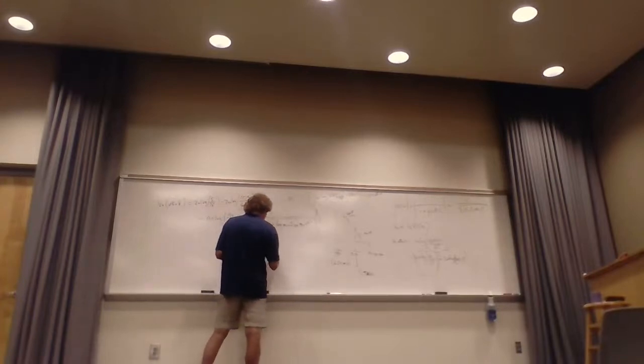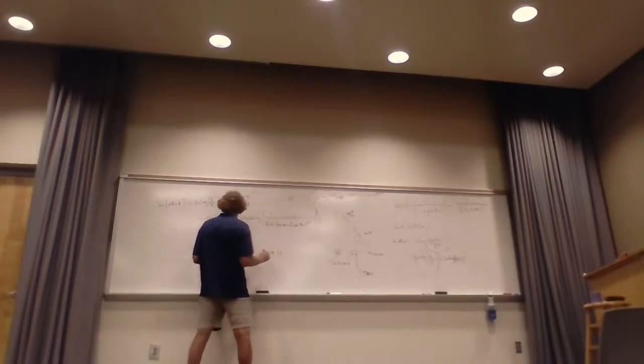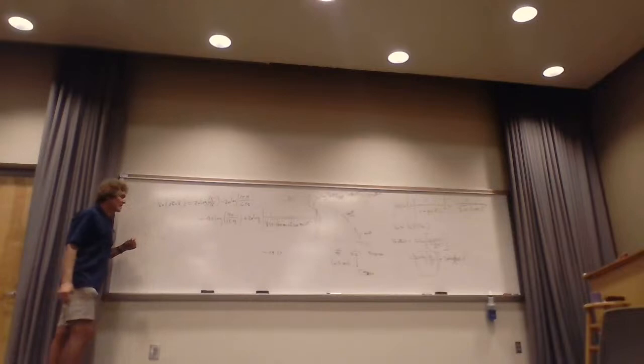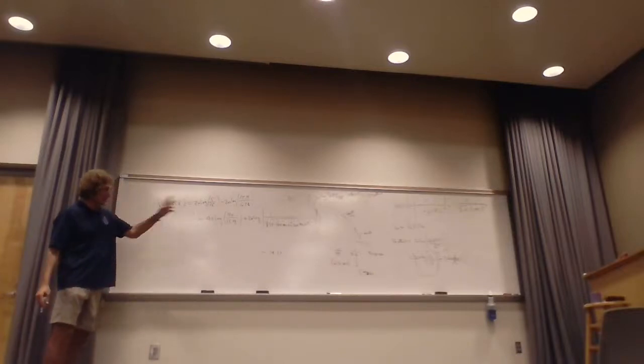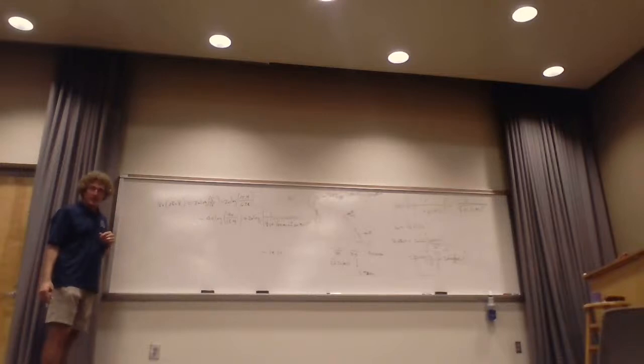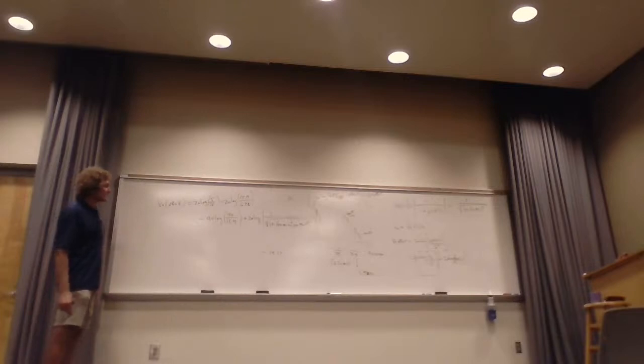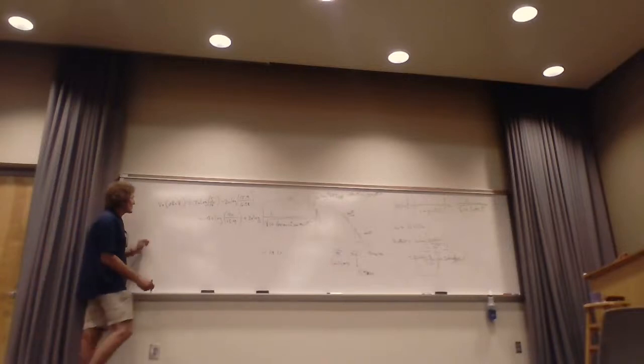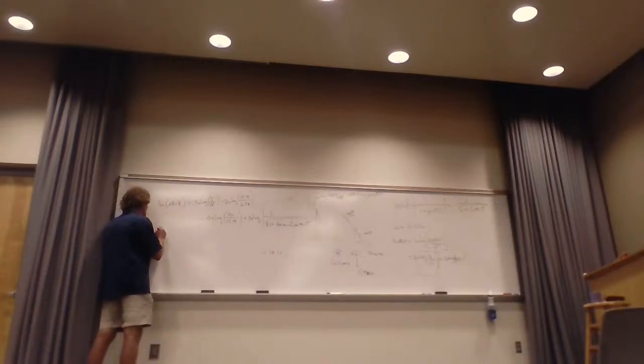This is about minus 19.18. And the rest of it, I forgot what it is, but I wanted to make sure you understand. That filter drops it down almost 20 dB more. That's the only real thing you're going to get out of this. That filtering is going to bring it down by 20 dB that high up, which isn't a lot.